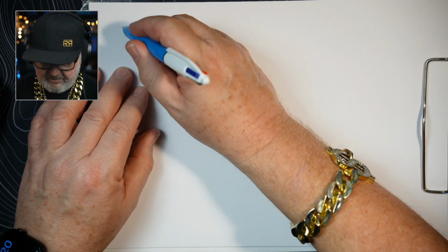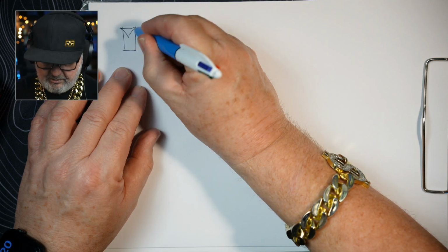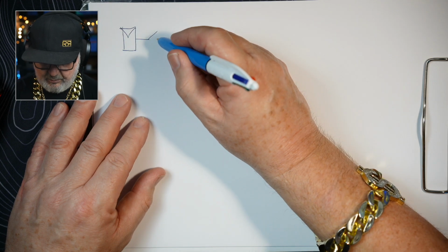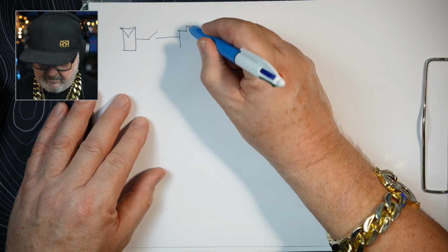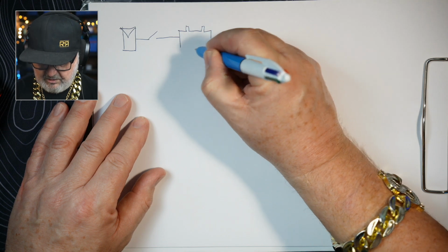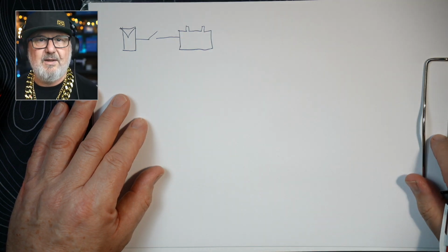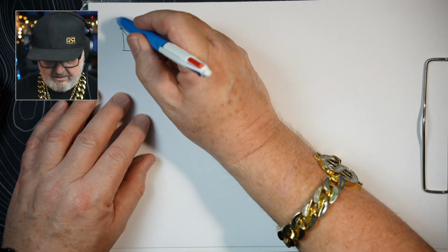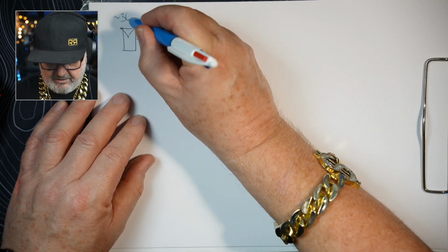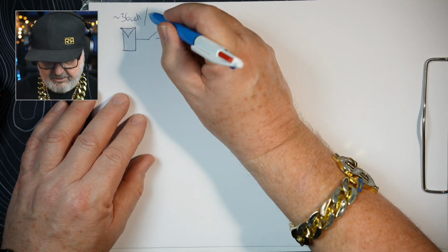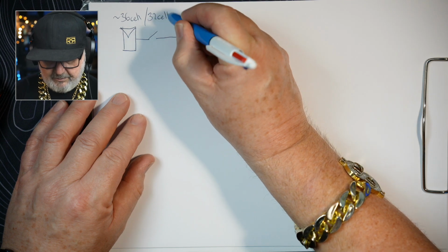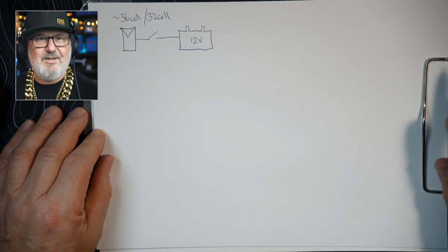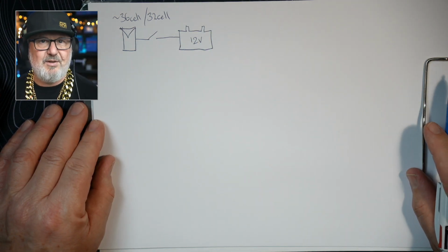The earliest systems were incredibly simple. And when I say earliest, we're talking the 1970s and before. You basically had just a switch connected to a battery. So there's your battery, and there's a switch, and that was it. That was your charge control system. So let's say you had a 12-volt battery here, and your panel would be a 36-cell, or sometimes even a 32-cell module. Because 32 cells never puts out enough voltage to overcharge a 12-volt battery. It's a really kind of lame solution, but that was a thing.